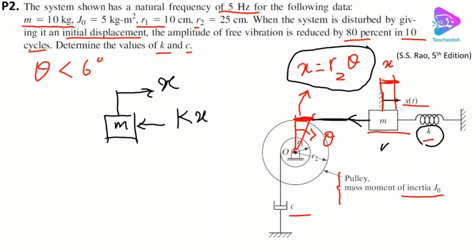In fact, we have a force against the motion because of this pulley and the rope on it. We can call it P. If it is P this way, it is in the opposite direction at the side of the pulley. You may remember that from dynamics. So we have P, and supposing that there is no elasticity in the rope, P is the same through it. This is all from statics or dynamics. So we have P here.